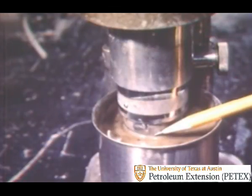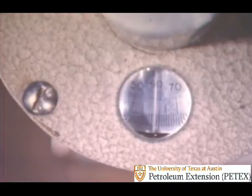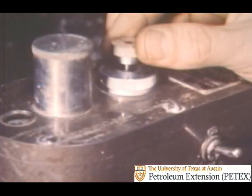To use the viscometer, fill a container with mud and place it exactly to the scribe line on the rotor sleeve. On a motor-driven viscometer, push this button down so the rotor turns at 600 revolutions per minute, or RPM. Turn the instrument on and wait for the dial reading to reach a steady value. In this case, it is 60. Now pull the button up so that the rotor turns at 300 RPM.